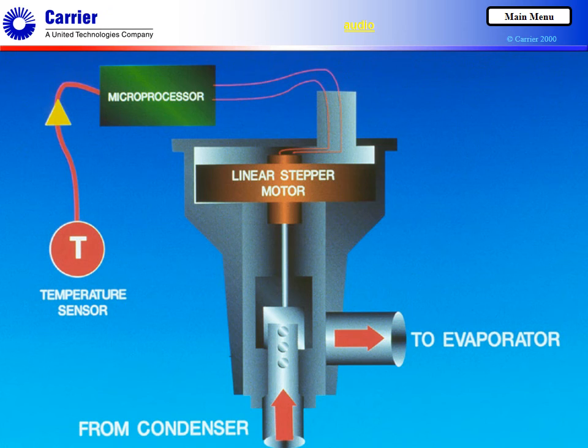One manufacturer uses this type of valve on reciprocating package chillers from 280 tons of cooling capacity instead of the conventional thermostatic expansion valve normally found on this sort of equipment. Like the TXV, this type of valve is designed to maintain constant superheat. The stepper motor gets its signal from an electronic control panel that's attached to an electronic sensor that measures refrigerant superheat.